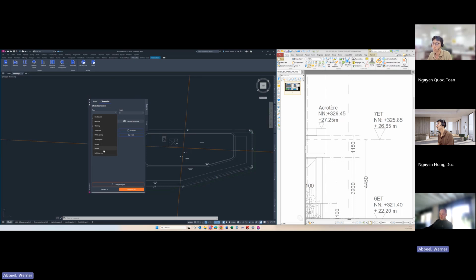So you can say, for example, a lifeline, the height is always 0.2. Align to roof. Why did they ask that? If you take a path, you can give it a weight of 0.05, for example, because it's just a cable. Okay.